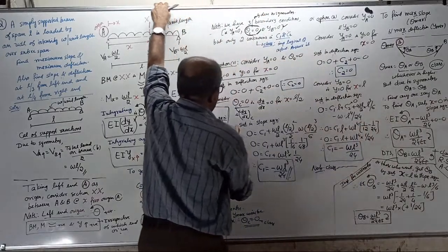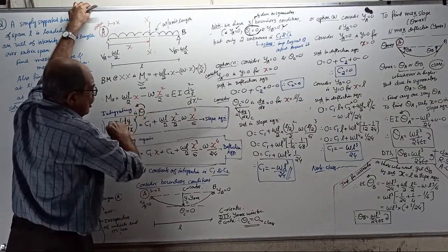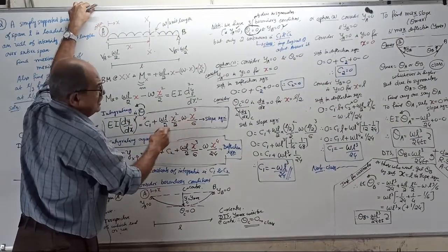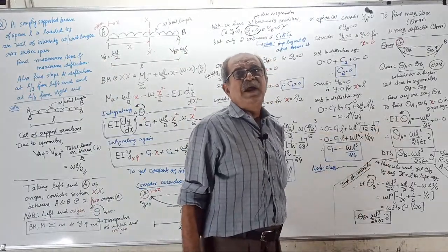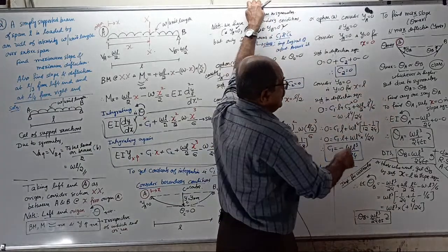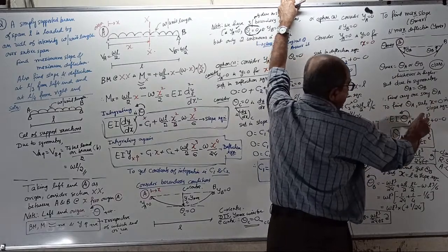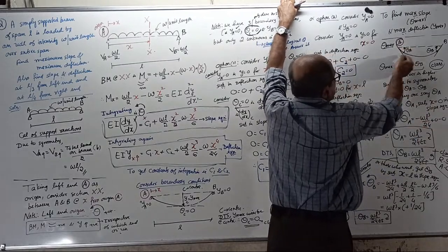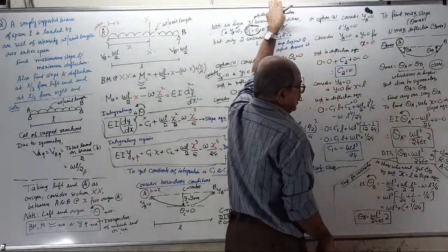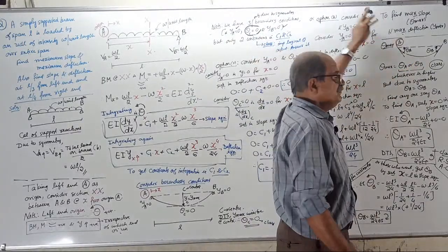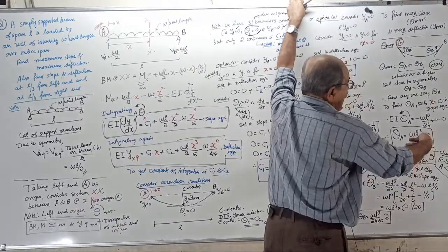See here, EI theta A in anti-clockwise equals C1. That's all. With the other terms 0, your theta A comes to minus WL cube by 24, so EI theta A equals minus WL cube by 24, or theta A equals WL cube by 24 EI. Anti-clockwise is positive, negative means clockwise. Slope is clockwise here, so I use a double arrow mark, since the sign comes later. Now you need not find theta B. Due to symmetry, theta B is WL cube by 24 EI only, anti-clockwise.